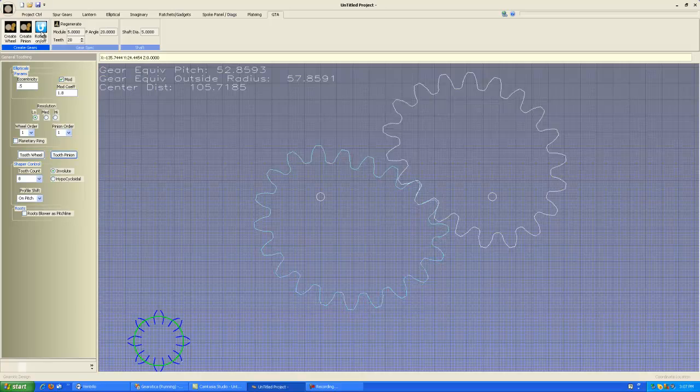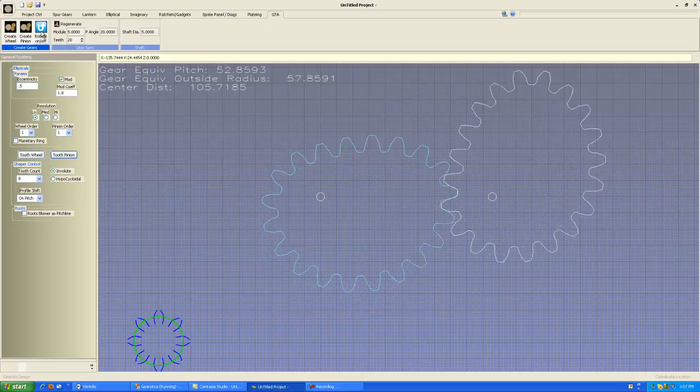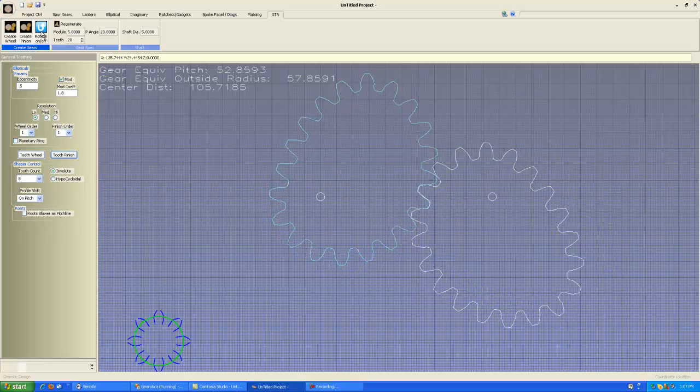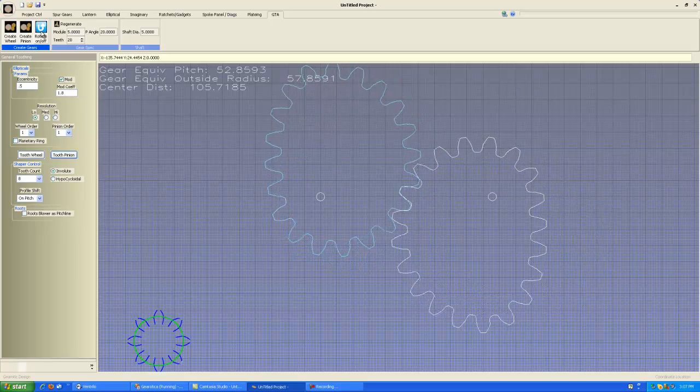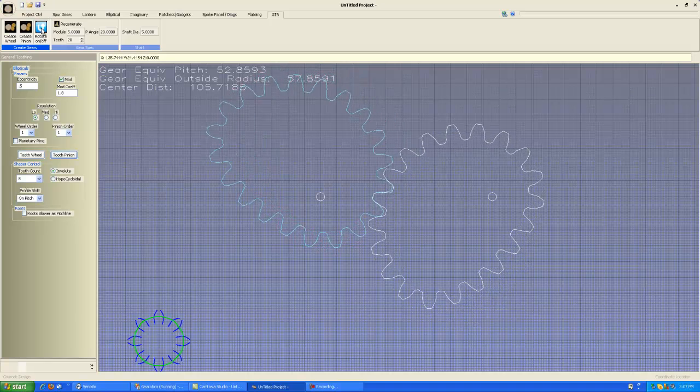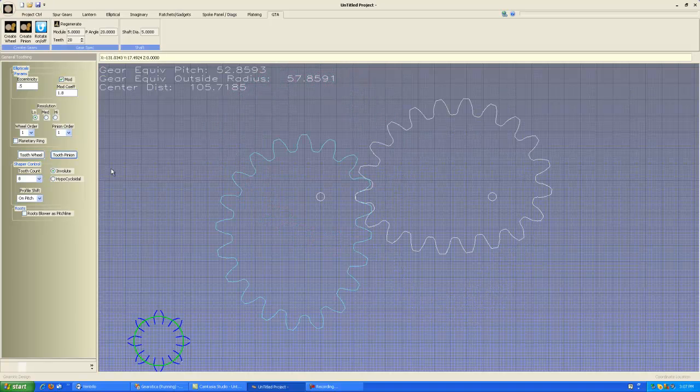A sign that an elliptical has been properly toothed is that the teeth are quite often asymmetrical, and as you can see, these teeth are different on one side than they are on the other, which kind of shows they're following the right formulas. One more thing that you should worry about is that you have the opportunity to shift your pitch profile. You can see that the teeth on these two gears are pretty much identical.